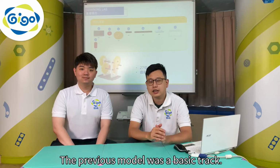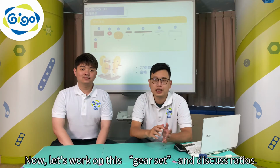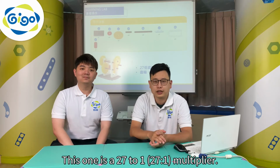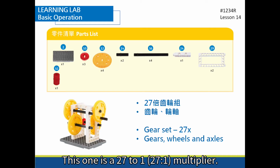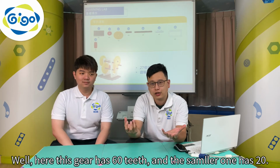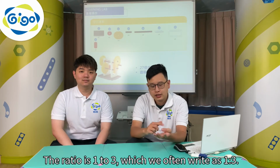The previous model was a basic track. Now, let's work on this gear set and discuss ratios. This one is a 27:1 multiplier. Where do we get 27 from? Well, here this gear has 60 teeth and the smaller one has 20. The ratio is 3:1. We often write it as 3:1.